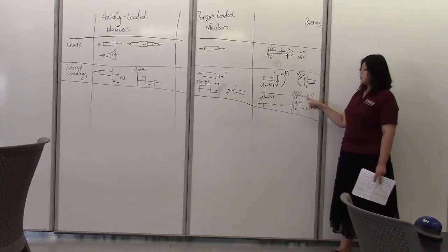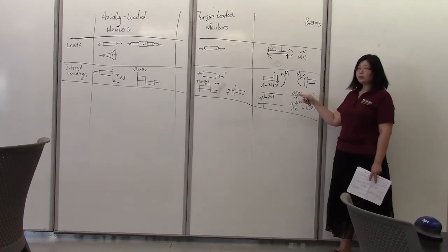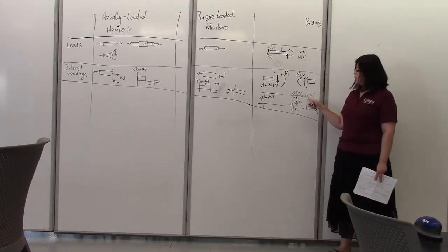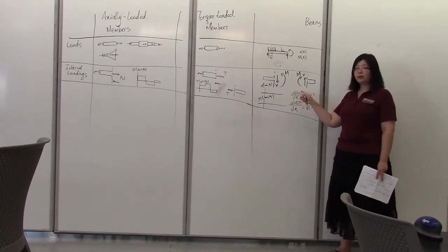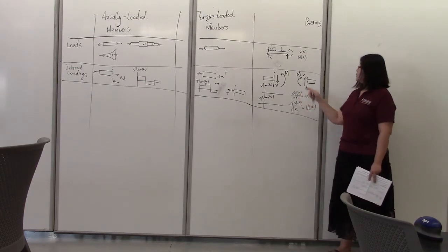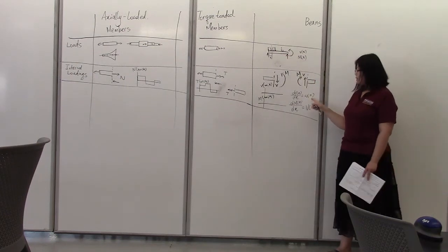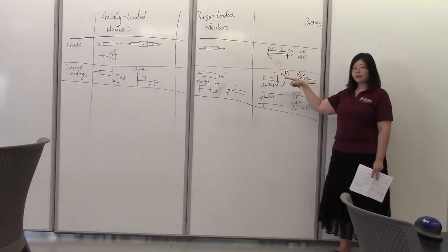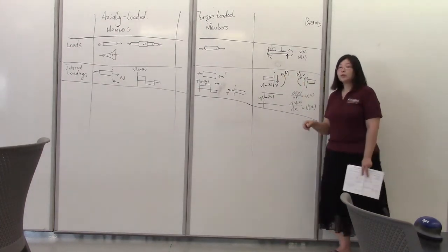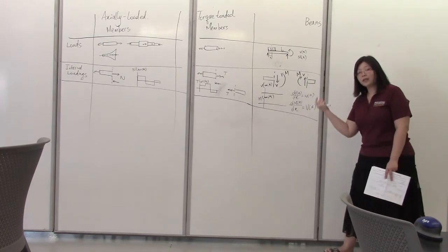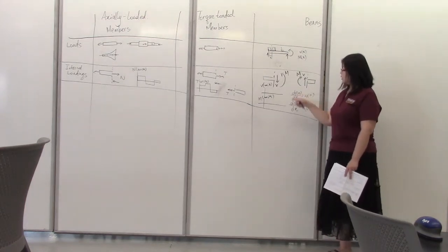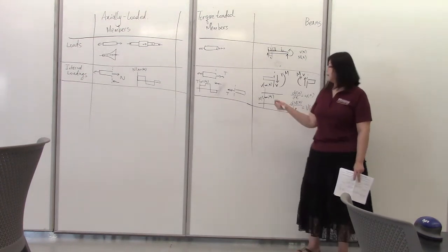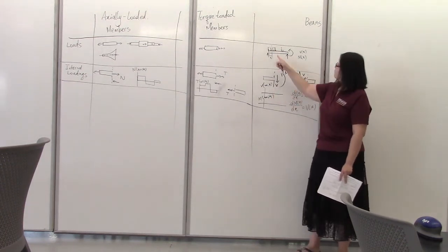So when there is a distributed load which is linear, then V should be quadratic, M should be cubic. When this is uniformly distributed, constant, that means V should be linear, M should be quadratic. Otherwise, for a segment where you do not have a distributed load applied, then V should be constant, so a horizontal line segment, and M should be linear. So you should first look at the shape of each segment of the diagram, then you could integrate each of these two, to find M and V at specific points along the beam.